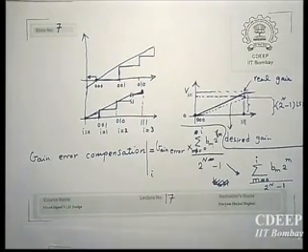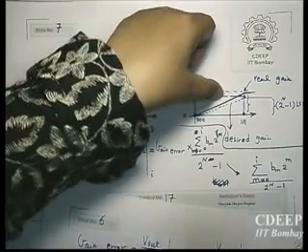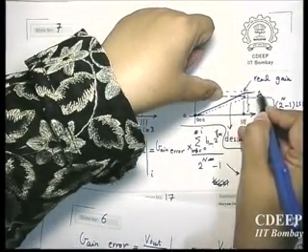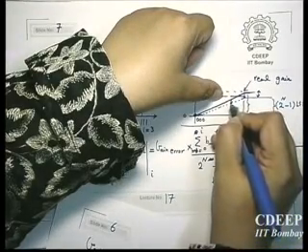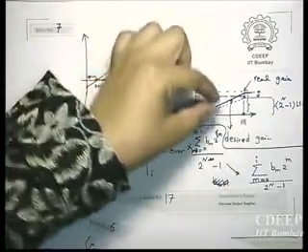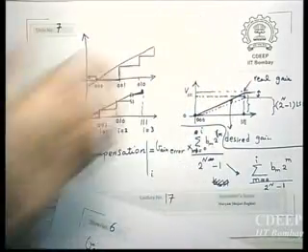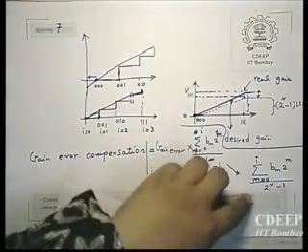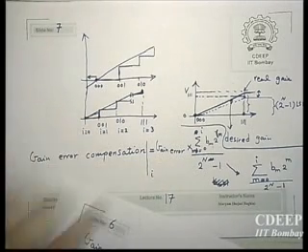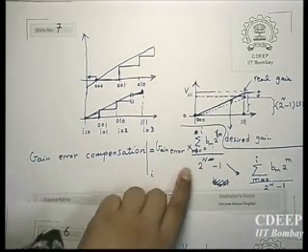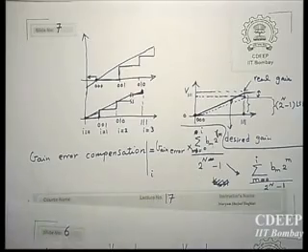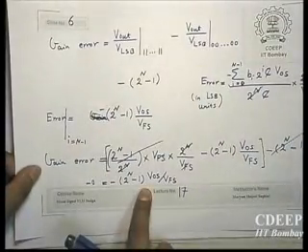This will be multiplied by gain error. This means that we are scaling. See, this is gain error at all 1. This is gain error in another code. See, it is getting scaled as we are moving towards 0. Therefore, we are multiplying by this value. We had one example from this gain error correction before. So we are just scaling that gain error. So after gain error compensation, this will get multiplied by gain error, and gain error was this value.